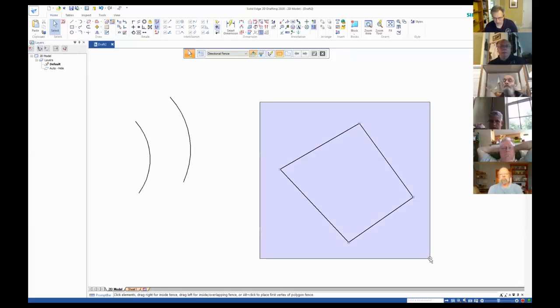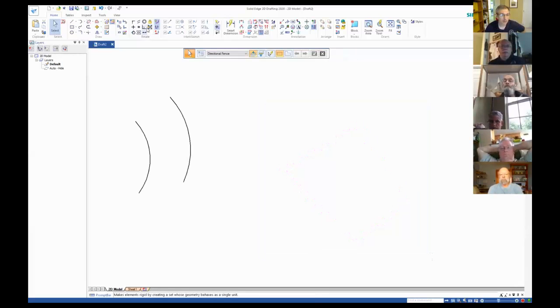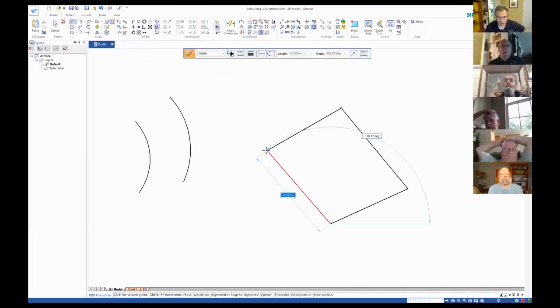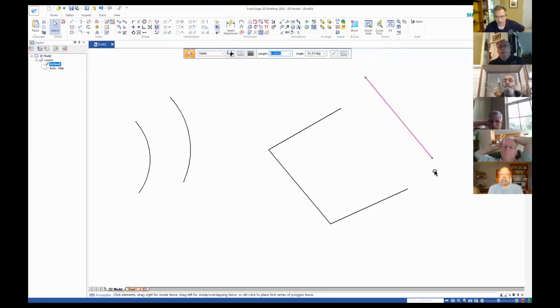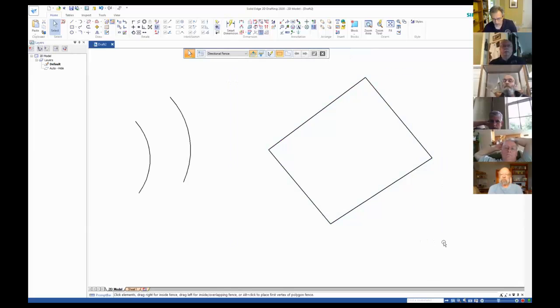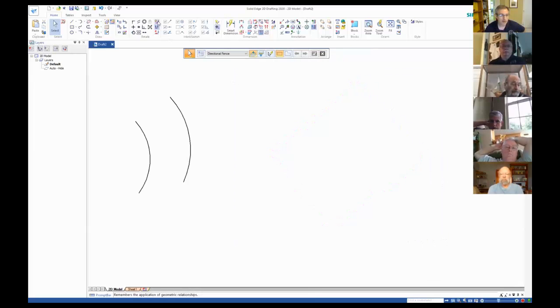And I can show you how that would work in every other program by turning off this maintain relationships and then creating the same kind of structure I had before. I have maintain relationships turned off. Now when I drag this line, it becomes disconnected. And if I wanted to keep that, I would have to readjust everything. And that's just very time consuming. So I always keep those relationships turned on. I'm going to turn them back on now.